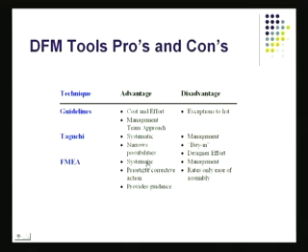As far as FMEA is concerned, it's a very systematic method. So this is also an approach that you could use in DFM. It will help you prioritize corrective actions. It will also provide guidance. What are some of the problems? You got to make sure you manage this whole effort properly. And make sure that you worry about the ease of assembly. This is something you got to be able to do when you're trying to do FMEA.